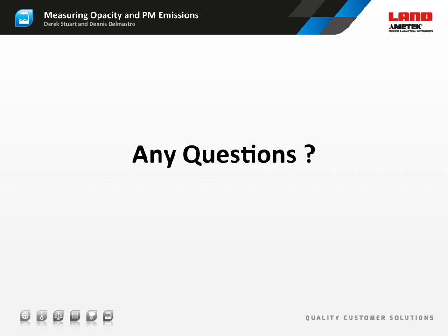So if any opacity monitor can measure dust concentration, why does one need a PM monitor? True, an opacity monitor can measure dust concentration after developing a correlation curve like a PM monitor, but there are lower limits to this measurement. Once particulate in the stack is at levels which result in opacity levels falling to 10% and below, then it is more accurate to utilize a particulate monitor. A particulate monitor is a high-gain instrument, so once there is any particulate in the stack, it can render a response. A PM monitor essentially works in reverse of an opacity monitor.